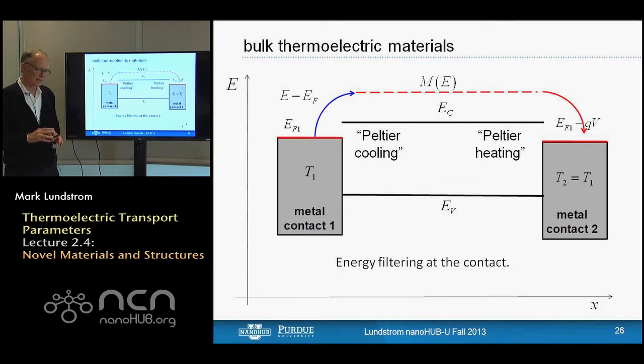Now, it turns out that there are some second-order effects. Once you start stacking devices together, there are considerations about how long it takes for some transients to relax, and spacings of energy relaxation lengths become important. And under certain conditions, one can find some benefits if one carefully designs a set of thermionic barriers in series.